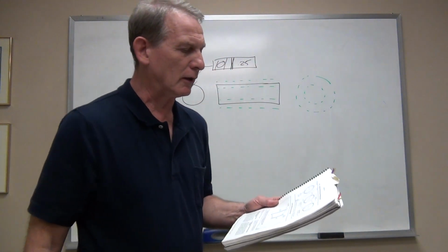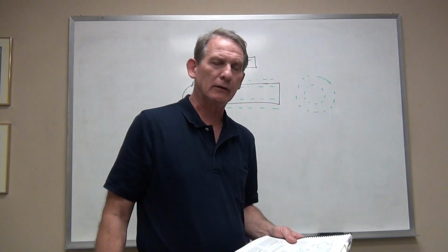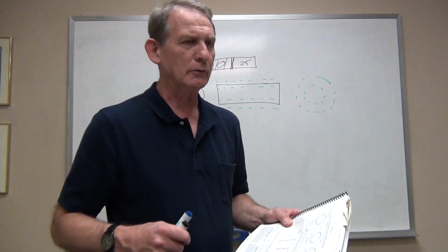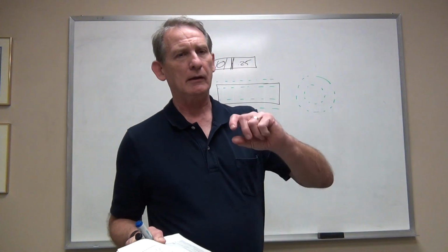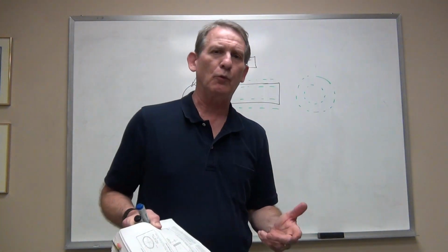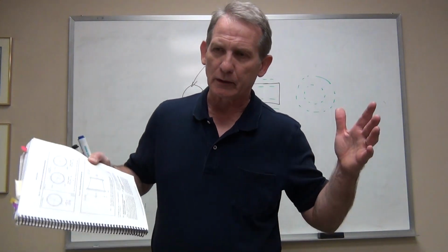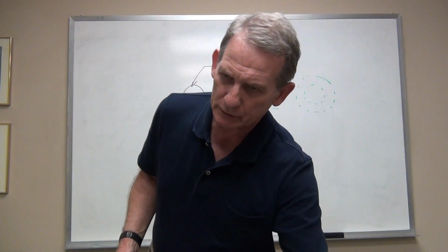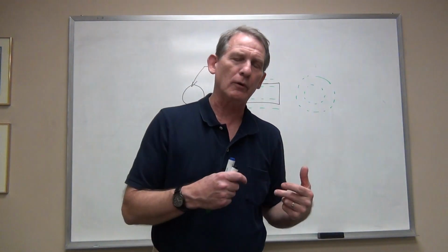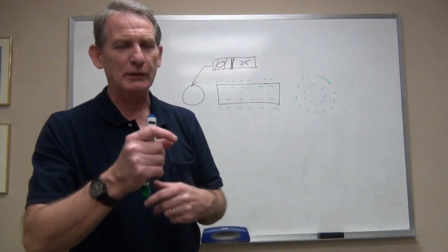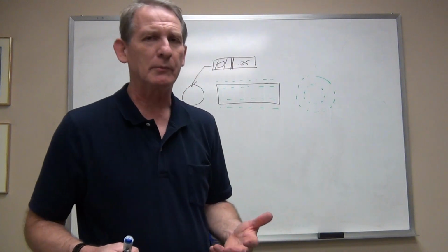Figure 513 talks about how we would average diameters to evaluate the circularity of something. So this would be used in an instance of something that is large but has a relatively thin wall, and on the machine, let's say you're turning a big 20-inch diameter ring that's real thin, and when you turn it on the lathe, bore it, it's nice and round, you measure everything, it measures good, and then you cut it off and all of a sudden it springs, it goes egg-shaped.